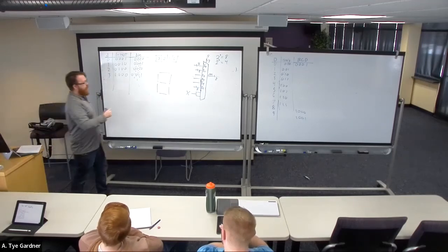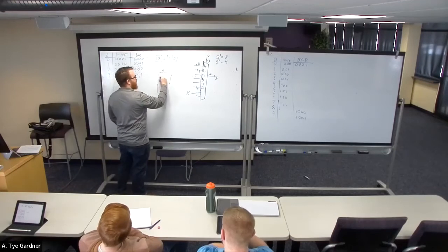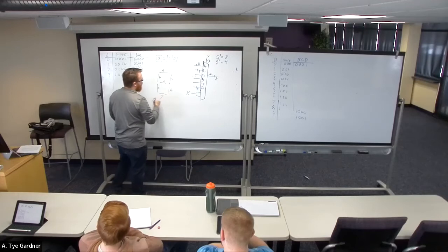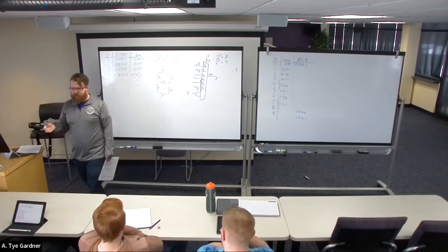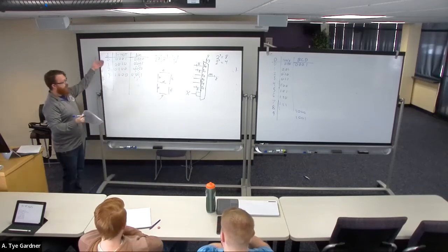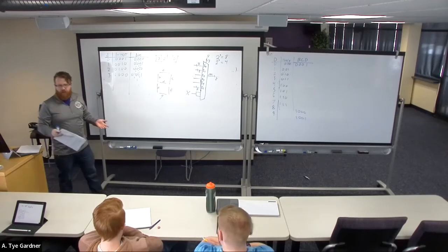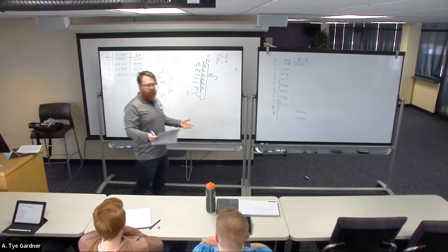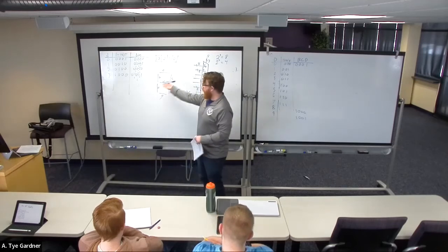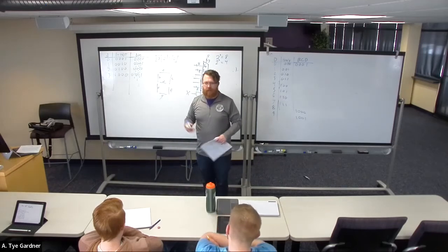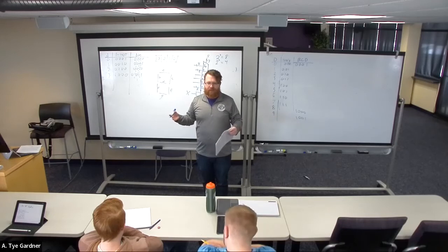And that says, well, if this is signal A, B, C, D, E, F, and G, each one of those is an output with an input corresponding to some decimal number. That's all that question was. It was an encoder. It was, how do we encode binary into 7-segment display? Decoders go the other way. Decoders take something that is encoded and pull it out.